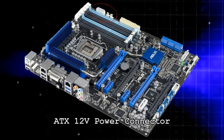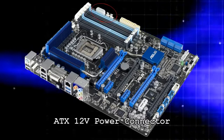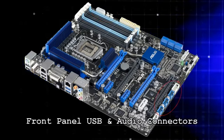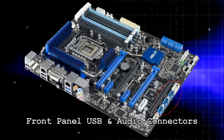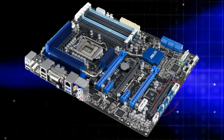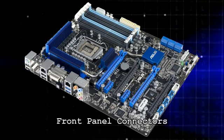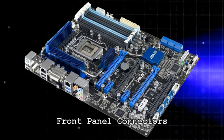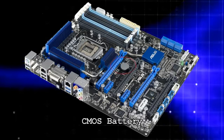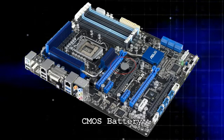ATX 12 volts power connector connects to the 4-pin power cable of a power supply unit which supplies power to the CPU. Front panel USB and audio connectors connect to USB and audio ports at the front or top of a computer case. Front panel connectors connect to the power switch, reset switch, power LED and hard drive LED of a computer case. CMOS battery supplies power to store BIOS settings and keep the real-time clock running.